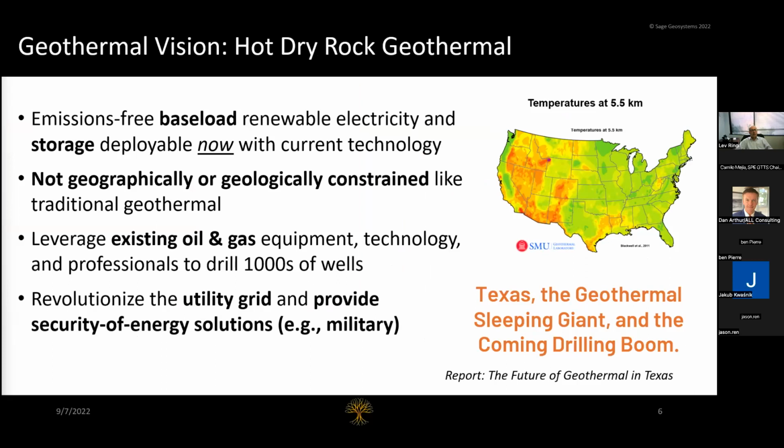But can we generate geothermal power from hot dry rock? If you live in Texas, let's say, as we do, we all know that there is a very good geothermal gradient. If you drill to 18, 20,000 feet, which we do for deep gas, you're at 200, 230 C or 400, 450 F, which is known to be more than enough to generate geothermal power.